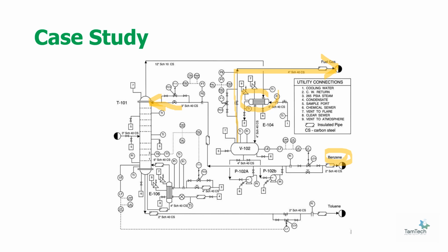Coming to the temperature, you can see it here. You have the TI, and also here is the temperature transmitter. Your temperature transmitter is actually controlled with the reboiler. This is the reboiler shown here. This is a different type of reboiler. You have the steam inlet and also the already cooled-down steam outlet, or condensate, we can call it. It is controlled with the help of this steam inlet. As you increase the steam flow rate, your temperature gets increased.